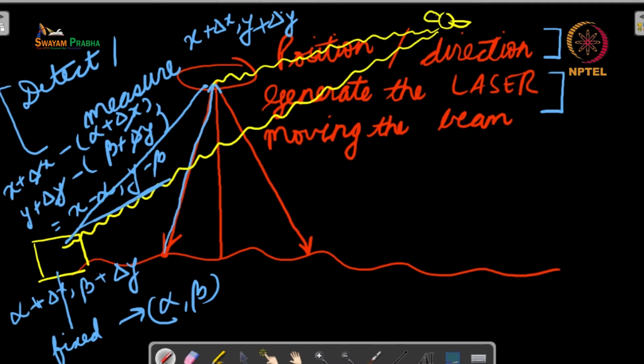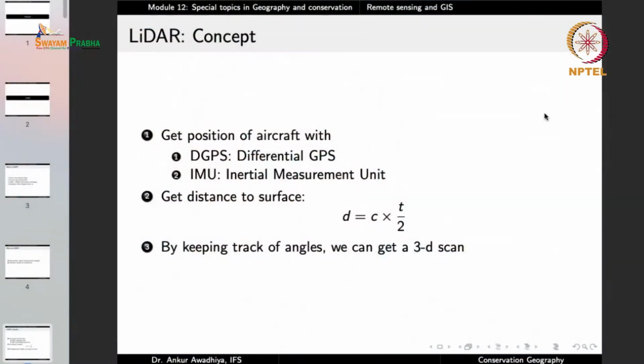So we take the measurements at two locations. One is the location of the aircraft and the second is the location of a ground point or a fixed station. We do a subtraction of both of these, and because the errors are the same in the measurement in the aircraft and in the measurement on the ground, these errors get cancelled away and we can figure out the exact location of the aircraft. So that is the utility of differential GPS.